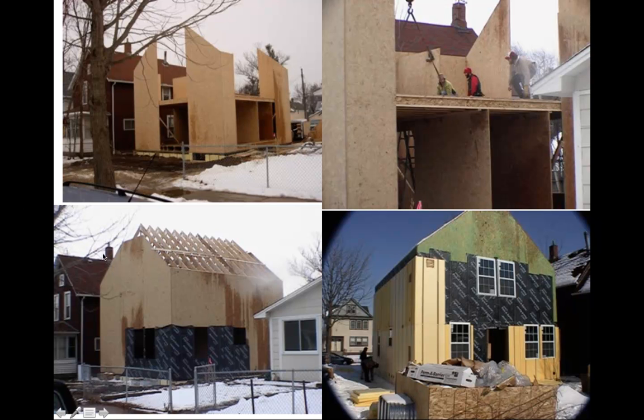So you have the loads coming down from the roof and from the snow load that's going to be supported by the column over this whole length. Well, if you think about a fairly narrow column over this whole length, that's going to be much more difficult, and it's going to be a much too long a buckling distance. So in building this, you actually use your second floor, or the I-beam to support the second floor, as a bracing system.